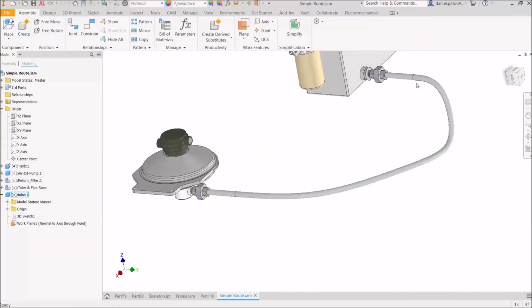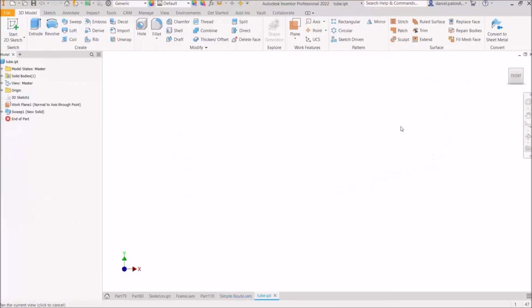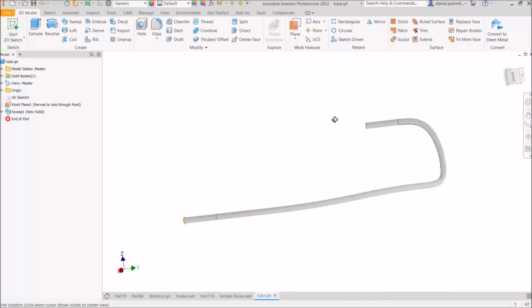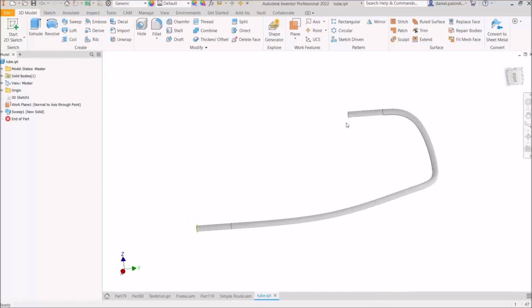And there we are. We've now created a part using 3D geometry. We were able to project out the geometry straight from the assembly. We could then create a spline and fully define that spline the way we wanted to, and then actually sweep it out. And you can see I can open that up and I can go and detail that part as an ordinary part. Okay, so those are some of the uses for 3D tools. Now, of course, there are many more 3D tools that you can work with, but those are just a few of them.